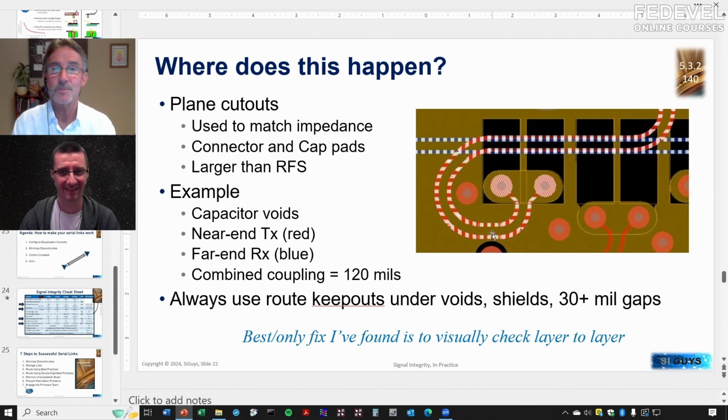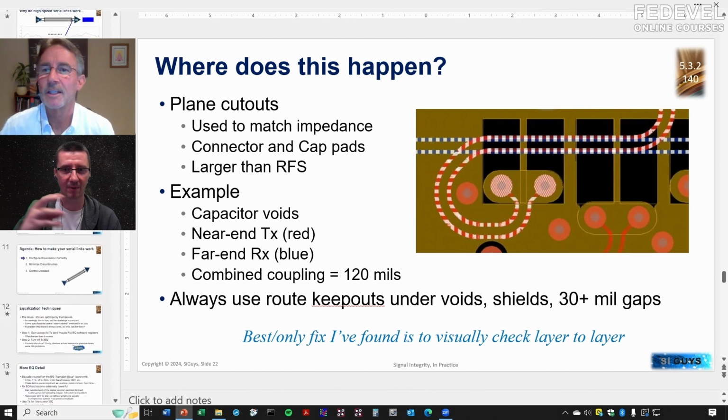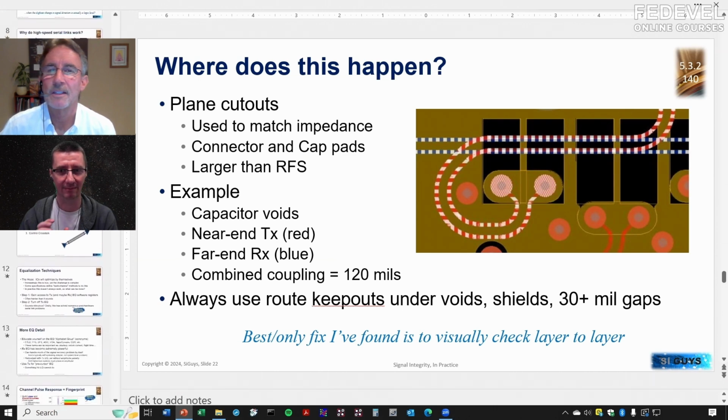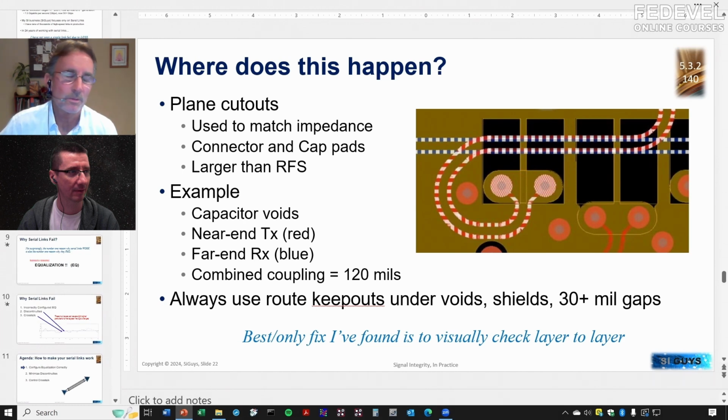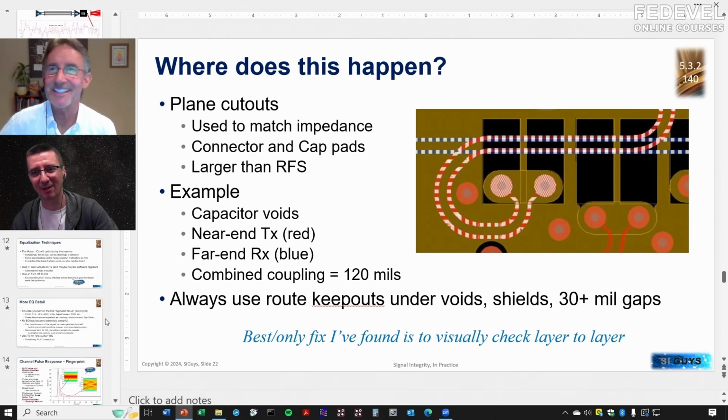Yes, bad feedback. We got a very powerful TX hitting an RX that is just about to get received, and so that's a lot of coupling, right? So even the direction is important, and the location where we are looking. For many years we've put TXs and RXs on different layers for that reason, so they don't crosstalk on each other. But even here they are on different layers, but you see there are openings.